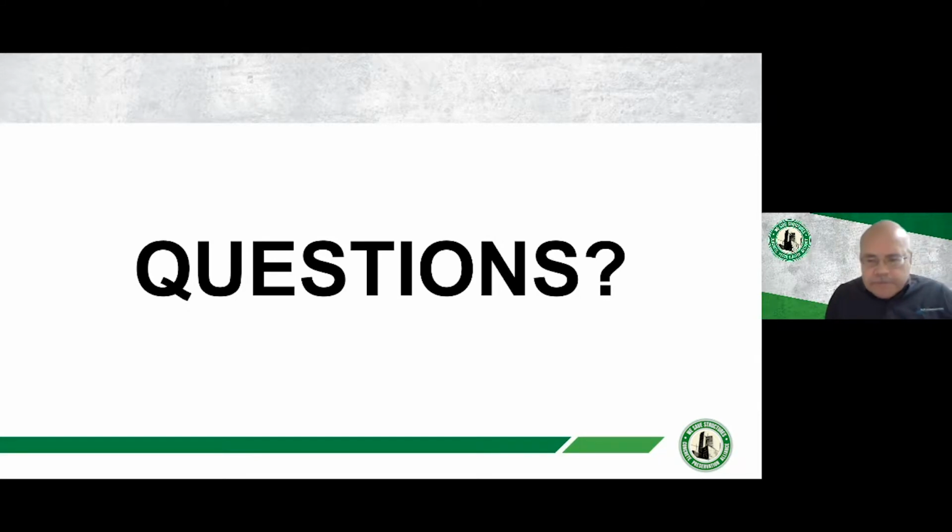Excellent. Tarek asked, can the GPR determine the effective area of reinforcing in the concrete, or is it just to locate the rebars and qualitatively see if it's in good condition? Good question. The GPR can verify first cover depth, very accurate for that. The lateral spacing of the reinforcing. What it cannot do is determine the bar diameter.